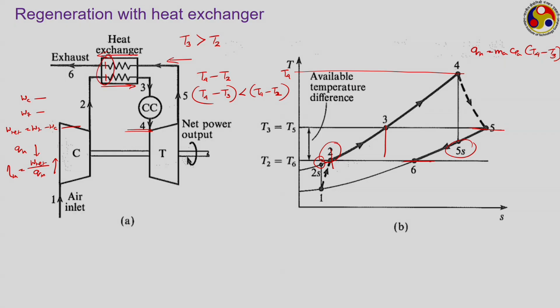So, gas temperature being higher, it is still able to add energy to the air stream, whereas towards the exit side where the air temperature is high, the gas temperature is also the highest. So, this counter flow heat exchanger arrangement gives us quite high effectiveness, and therefore, we can recover a significant amount of energy from the exhaust gas.